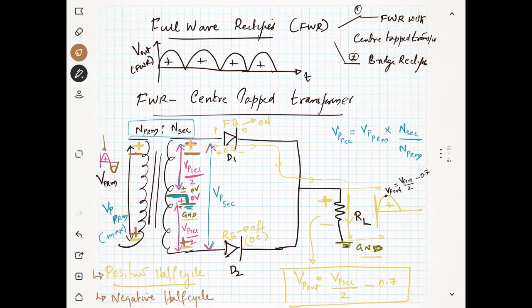So you see here, this negative is connected to D1, to the P side. That means this diode is reverse biased. That means this diode is off now. Then what will happen? You see here, in the lower side it is positive. That means this diode, D2, has positive connected to the P. That means it is forward biased. That means this diode is on. So the diode D1 becomes off and D2 becomes on.